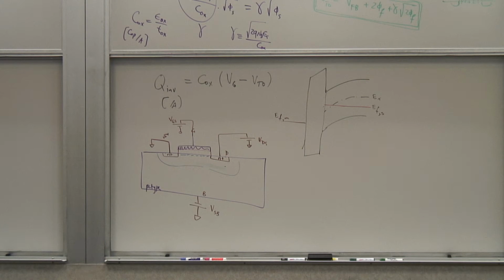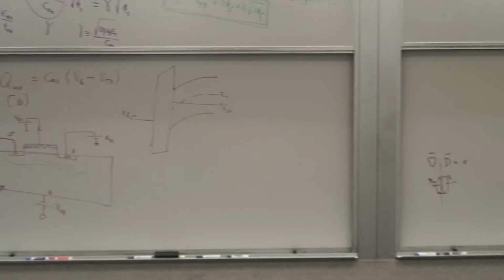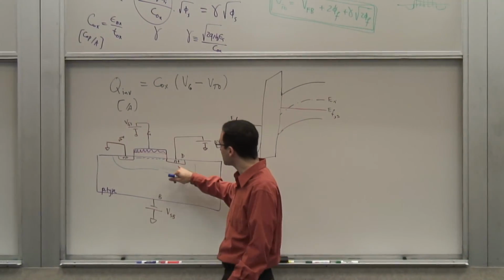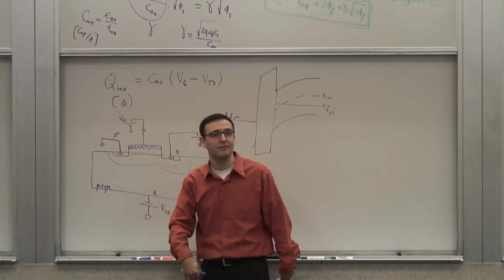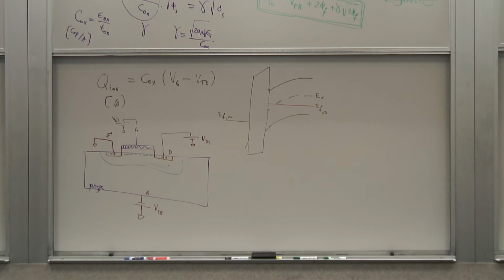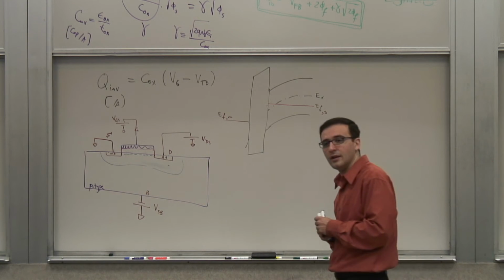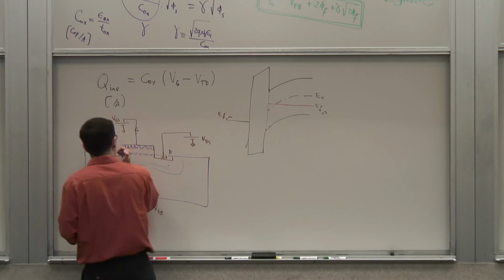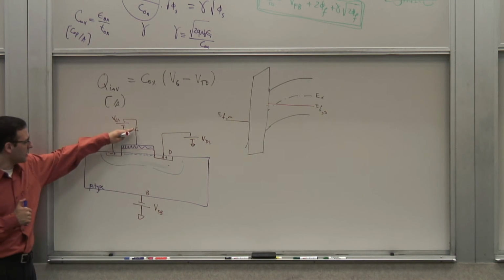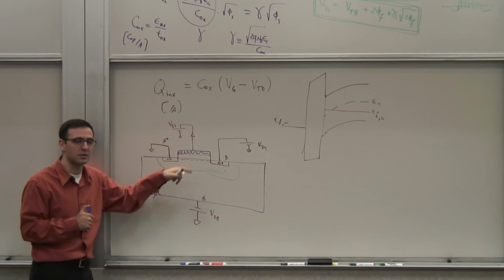So you see the limitations for that when we went to kilohertz. For a MOS capacitor, once we went above kilohertz or tens of kilohertz, it just did not react fast enough. But this time, since I have these sources, it can react very fast, and you have MOSFETs that operate up to tens of gigahertz, hundreds of gigahertz nowadays, right? That's the reason, because you have a source of electrons right next door. So when you apply this voltage, most of the electrons are really coming from these guys.